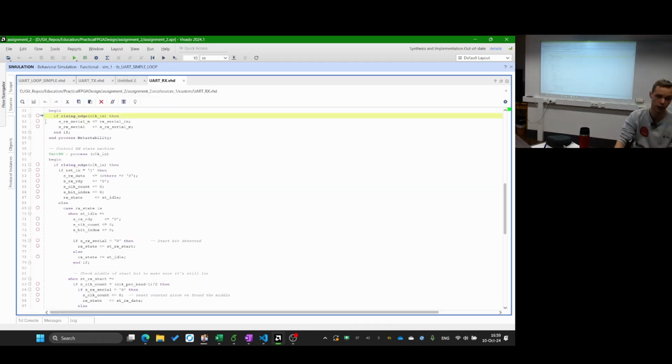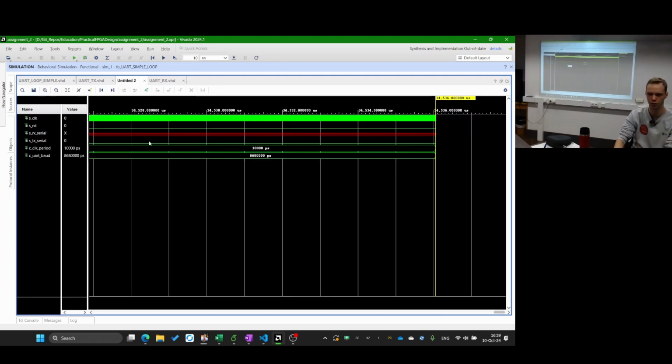And then it's even in Vivado, and older tools don't support that. You can put a debug breakpoint, so you actually can debug the code like other code, and it will always break at that point, and you can look at how my simulation looks exactly when it comes here. Of course, alternatively, I can also just go here and look for when the signal changes and trace that.